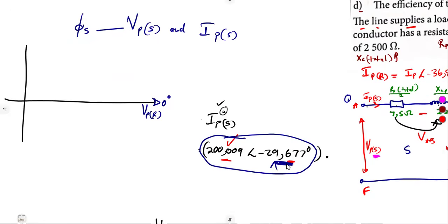The angle there is showing us from the voltage, which is at reference, from 0 degrees. It is negative, so negative is clockwise. If we are going this way from the reference, those angles will be negative. From the reference at 0 going this way, those angles will be positive. Remember that, guys, from your N4.